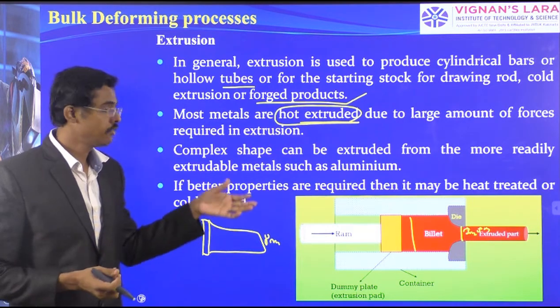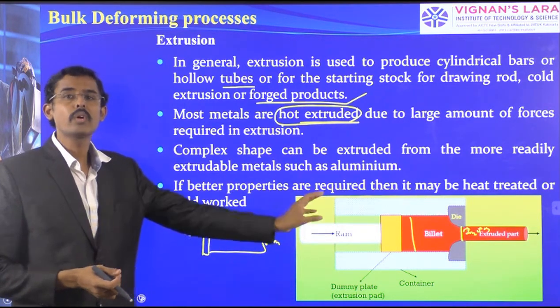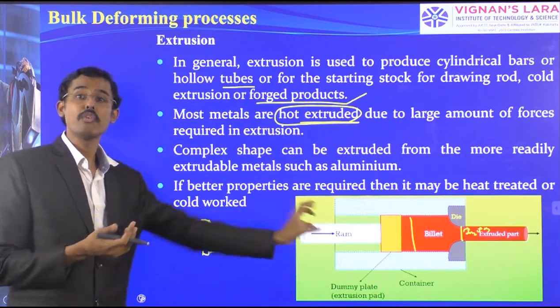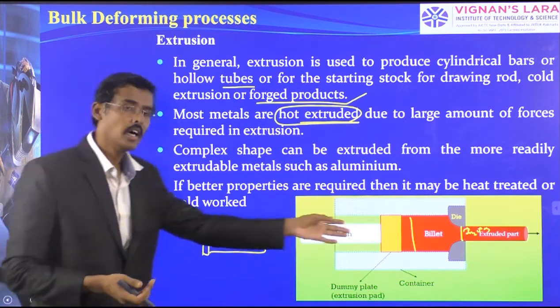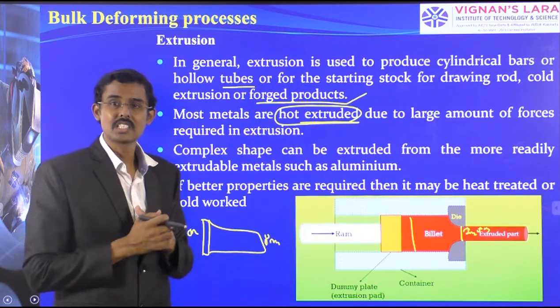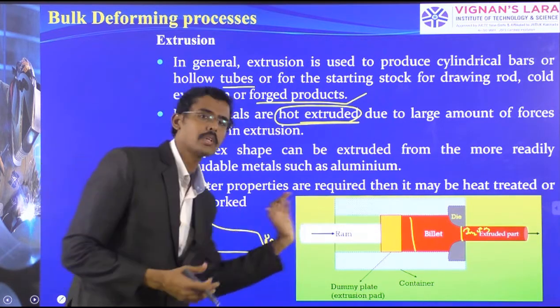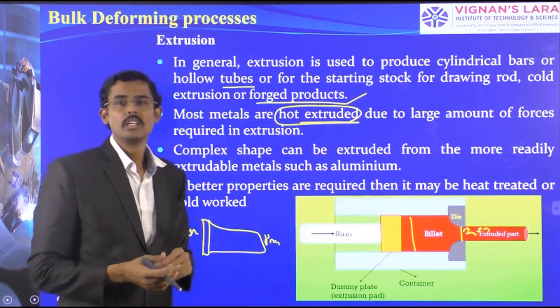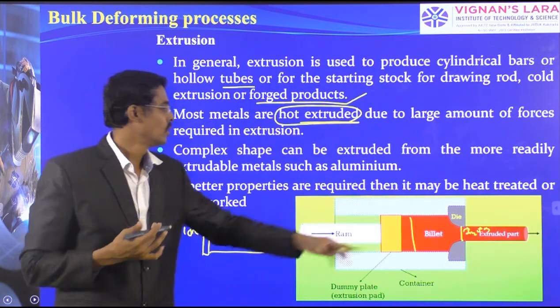Therefore, if we are doing the same extrusion process in cold working, more force is needed because it is not red hot. It restricts, ductility will not be there. Then we should press more, we should be pushing harder here. It may crack and damage the workpiece.